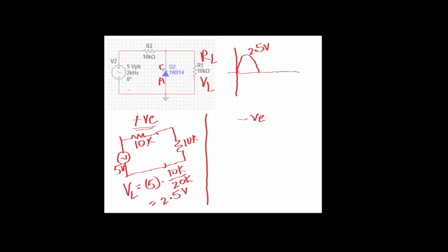During the negative half cycle, that means the input signal is, if you observe, the positive is basically applied to the anode and the negative being applied to the cathode. So the diode will be forward biased. When the diode is forward biased, there is going to be 0.7 volts across the diode. Remember when it is forward biased, you need to carry the polarities. The cathode is on the top, which is the negative. The anode is at the bottom, positive.